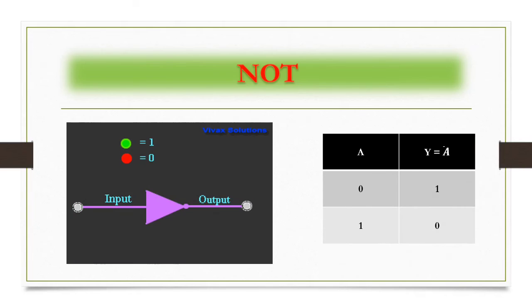This is the truth table. The bubble at the end of the NOT gate represents a signal inversion or complementation of the output signal. But in some cases, bubbles are also present at the gate inputs to indicate an active low input. And the inversion of the input signal is not restricted up to NOT gate but also can be used on any digital circuit or gate.